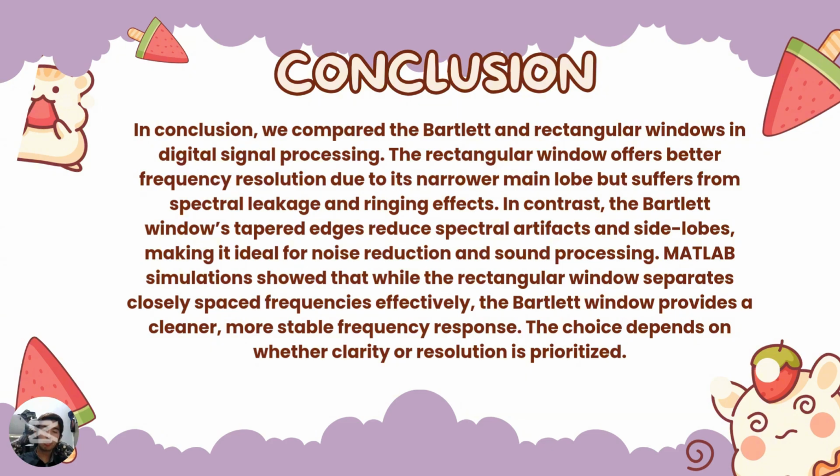So the choice between the rectangular and Bartlett windows depends on the specific requirements of the application. The rectangular window is preferable when frequency resolution is a much higher priority, whereas the Bartlett window excels in scenarios demanding better side lobe suppression and reduced spectral leakage.